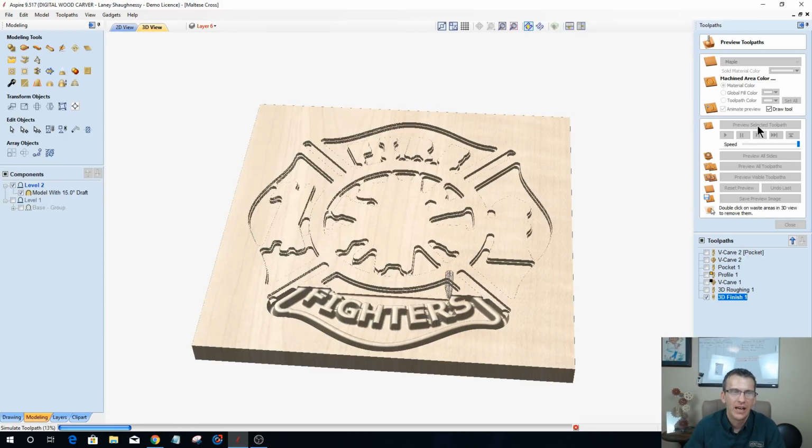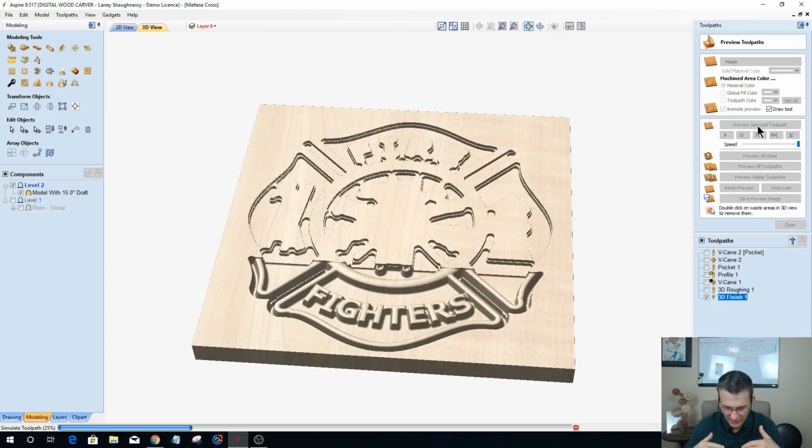It surely did. It was 1.999 in both the gap offset X and Y, as well as in the row displacement and the column displacement. So it was 1.999 in all four boxes, and it created that array offset perfectly.